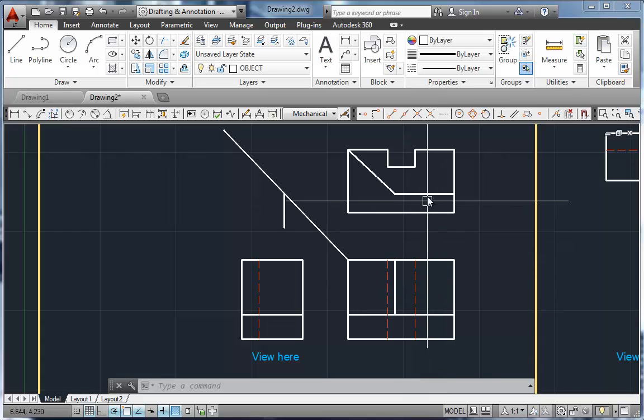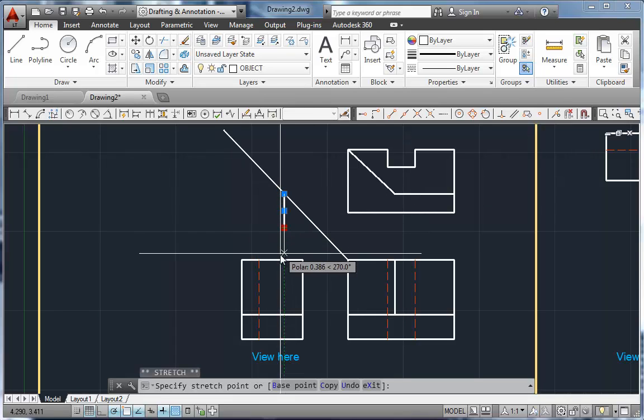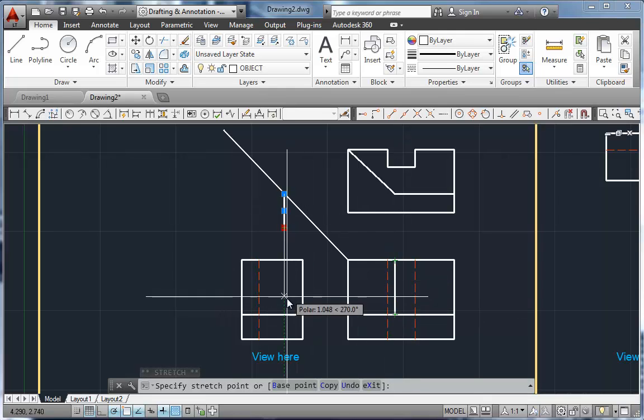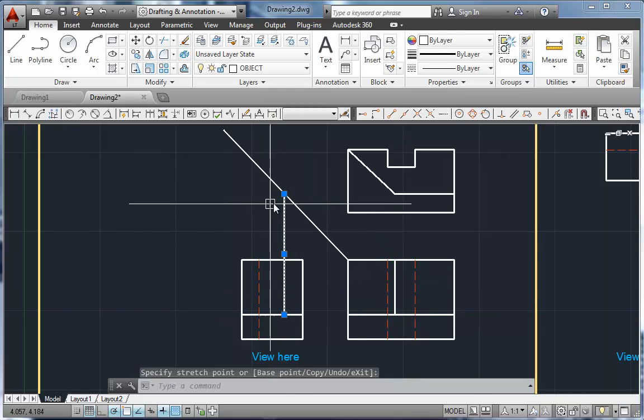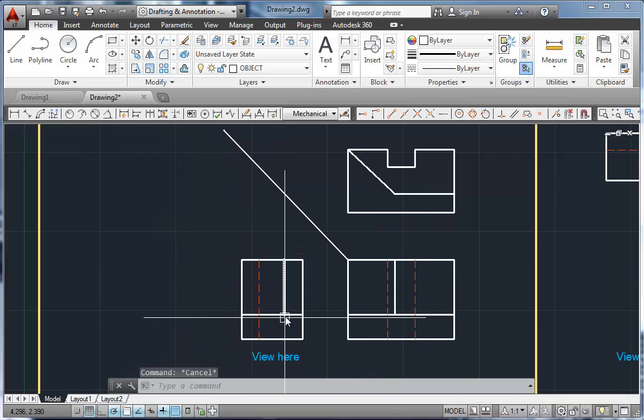You remember our rule, edge view, and as a box or a plane, that means in this view it's going to be an edge view this far back. So I could project this over, which I did, and this is that line. I'm going to project this down, and that corner stops right there. So I'm going to bring it down to there. Bring this down to the top, and I would see that object line there.